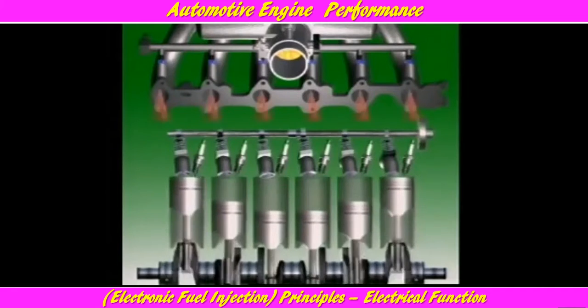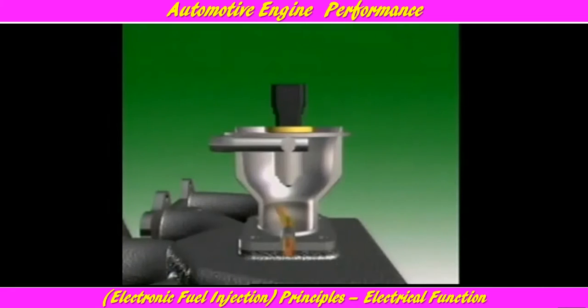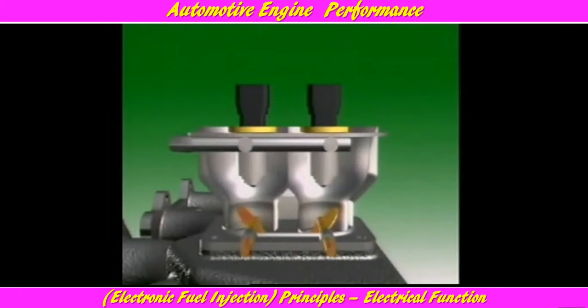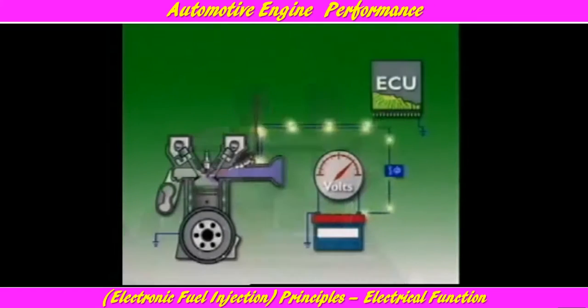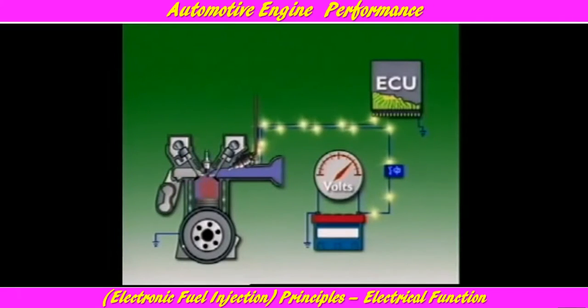In a six-cylinder engine, the injectors are triggered on every third ignition pulse. In throttle body systems, the central injector is normally triggered on every ignition pulse. However, if there are two injectors, alternate triggering may be used. At idling speeds, the frequency may be less to provide finer control.